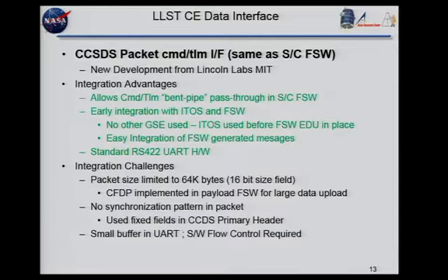So for dealing with these interfaces, and there was one on the Star Tracker as well, it was the same issue. We ended up just looking at the primary header for the CCSDS packet. There's enough information in there to form a little sync word because you know the range of the app ID. There are some bits that are always set, and the length field you can kind of know is going to be in a range. So we used that for syncing. And I did a lot of testing where I pulled wires out and put them back in to make sure that if we got out of sync, it wouldn't ruin a whole pass and lose all the science data for a pass.